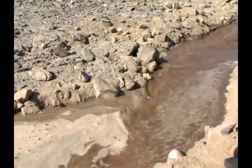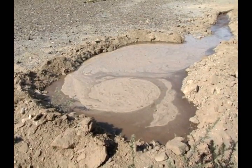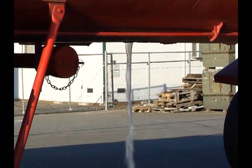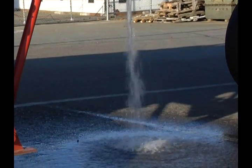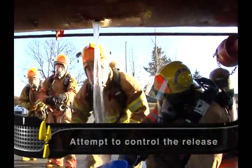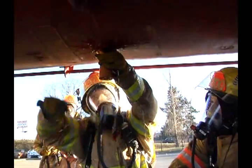Groundwater under the soil can also become contaminated if the product leaches downward to the water table below. There are a few general guidelines for hazardous material spill control that should be remembered. First, attempt to control the release at the source as soon as possible. It doesn't make sense to keep digging when you haven't tried to stop the leak.